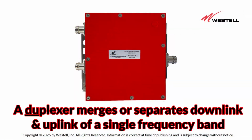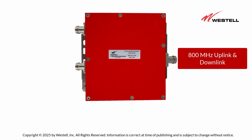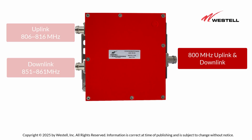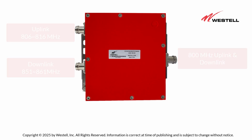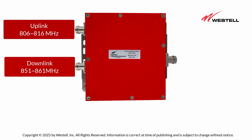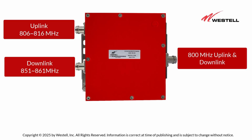A duplexer merges or separates downlink and uplink signals within a single frequency band using bandpass or notch filters. It effectively isolates uplink and downlink bands from each other. A duplexer can receive the entire 800 MHz band on a single input and then split the signals into two outputs, one for the downlink band and the other for the uplink band. Conversely, it can also accept separate uplink and downlink bands to generate combined uplink and downlink outputs.